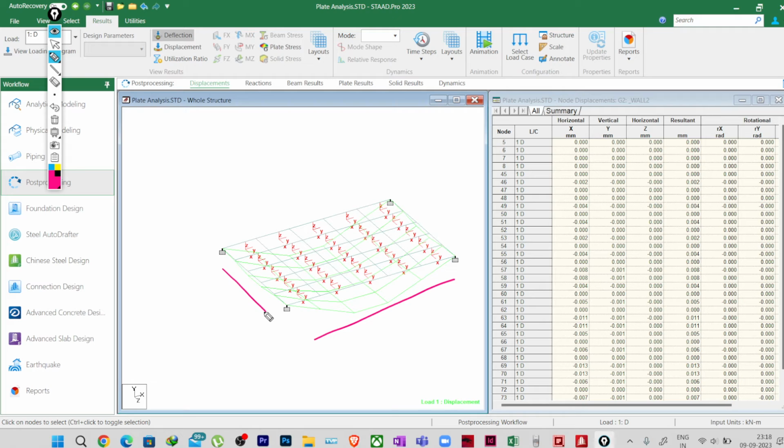Secondly, the higher bending moment, obviously, will happen at the center of the slab, somewhere here. Center of the slab or center strip of the slab. As the z direction is upwards, the sagging moment is dominating in this case, or I should say, tension at bottom.